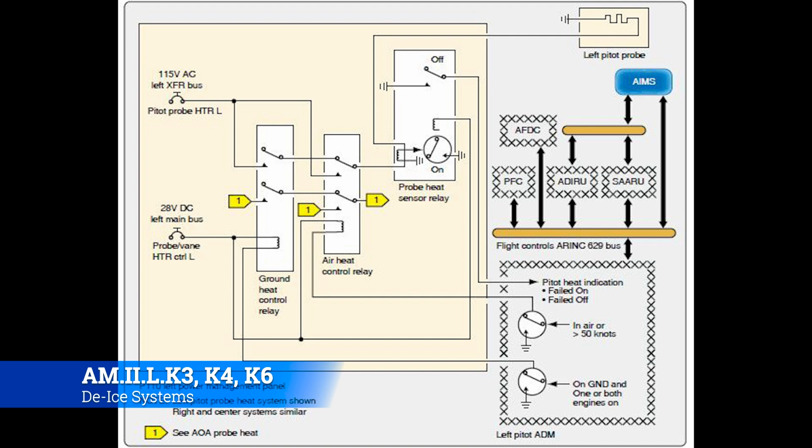A lot of times with these systems, the symptom is not necessarily the problem. It's just where it's manifesting. You're seeing that the pitot heat didn't come on for the left probe, but it's not necessarily the pitot tube that's actually the problem. It could be any of those other things.